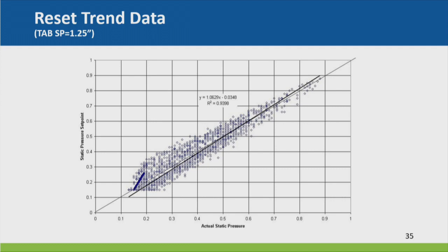And in this particular case, I put a minimum of 0.15 on the trim and respond block, so it never could go below 0.15. Now I put 0.05. There's no minimum, you can't be too low, because if it's so low that somebody wants more static, it bumps up automatically, you know. So I had it artificially low, and it's like wasting some energy there. So no need to make it do that. Let it go all the way down. So you can see that most of the time we're doing 0.15.